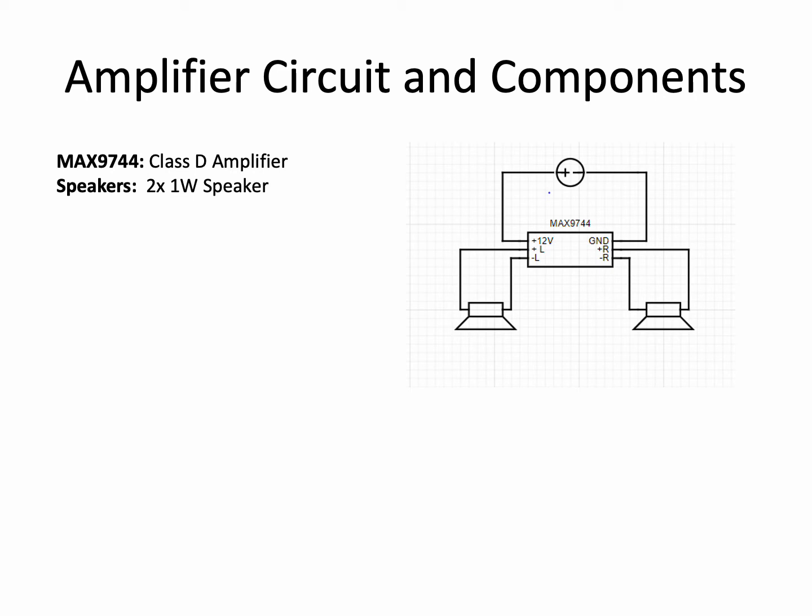The amplifier is powered by the device-wide 12-volt bus and receives a stereo, unbalanced analog signal from the Raspberry Pi. During testing, our team encountered errors with the Raspberry Pi's onboard audio output and DAC, so a small USB sound card with a separate 3.5mm output jack was used to convert the digital audio from the Pi to an analog signal that could be amplified by the board.